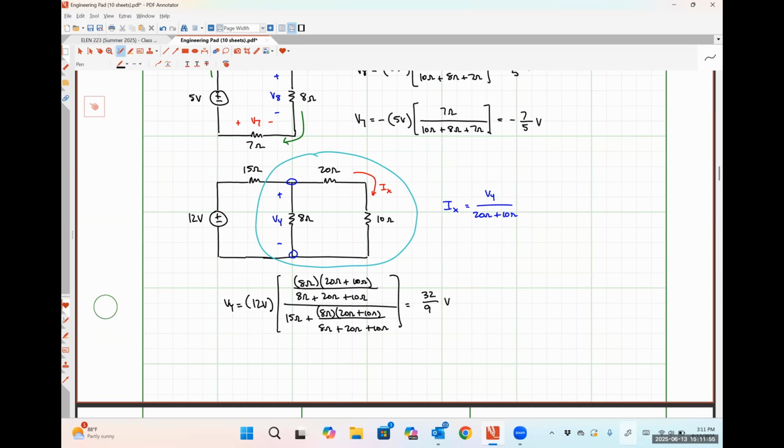So for those of you that are still working on homework set number 3, if you look at problem number 4, you can use voltage division to find that voltage V1, and then a second application where you treat V1 as your known voltage to find that voltage V2, and then use that to solve for the current I4 instead of fully collapsing the circuit down to where it's just one small loop and then expanding it to the right over and over again. You can do effectively a double voltage division and then Ohm's law in order to get the results that you're interested in for V1, V2, and I4 very quickly, as opposed to brute forcing it just using specifically KCL, KVL, and Ohm's law. And the method for doing that is very similar to the example problem that I just worked. Okay.